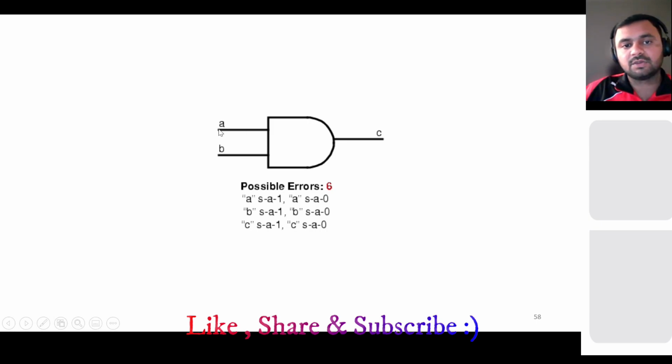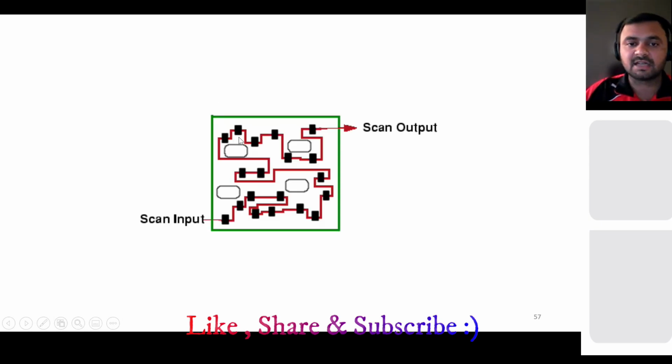Similarly, if it is connected to ground, this will be 0, so you cannot detect it as 1 here, 0 here, because you need to force the opposite value. Whatever node you want to test, if you want to test it is stuck at 1, you need to force it to 0 to see the behavior at the output. And if it is 0, you need to force it to 1. But if it is connected to VDD or ground, you cannot change it. That is why we need so much architecture for testing.